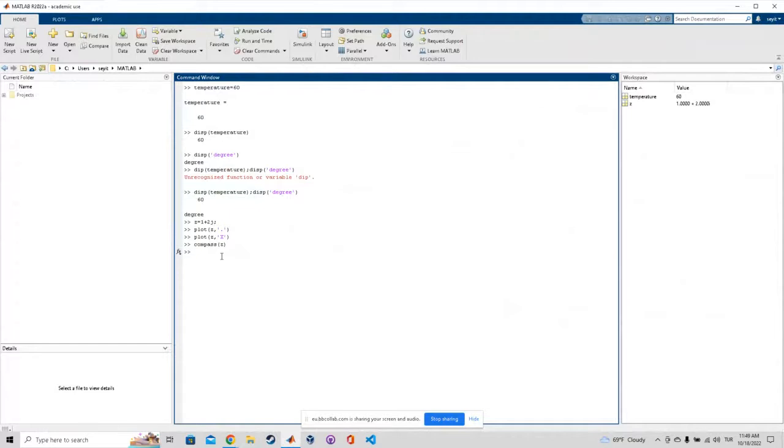Okay. Let's say we have a vector and we want to get the transpose of it. Let's say a equals, open your parentheses, 1 2 3 4, right? You hit enter. This is your vector, and you want to define a vector b as the transpose of a. When you transpose a vector, you take the row and turn it into a column. You hit it, it will take the transpose and define it as b. You just add this sign here, and you will get the transpose of this vector.